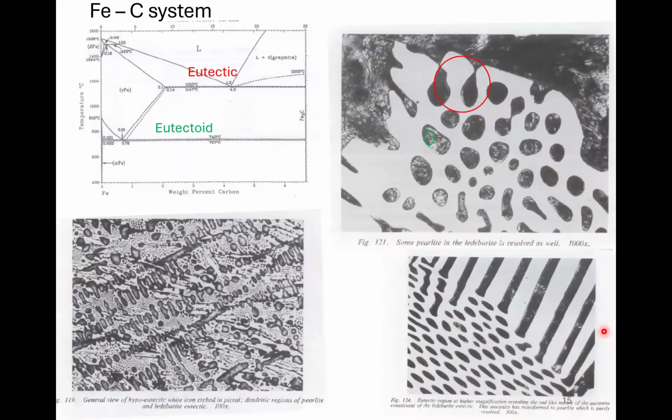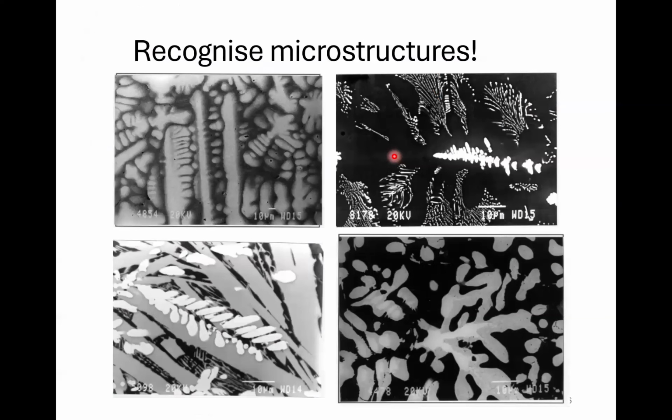And then this I pinched, I use it in teaching. There's the eutectic, it's at higher temperatures. There's the eutectoid at lower temperatures. This is the sort of diffusion distances from there to there that you've got at liquid. And if you look in here, you can just see some lines, and that's what's happening in that reaction, the eutectoid. And this, once you understand this, will actually help you interpret that microstructure. All good fun.